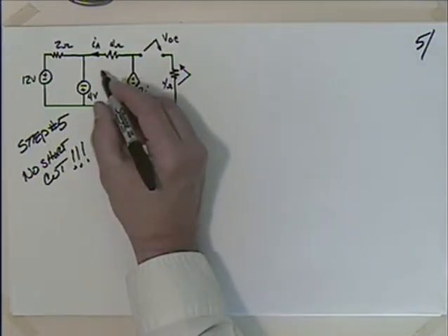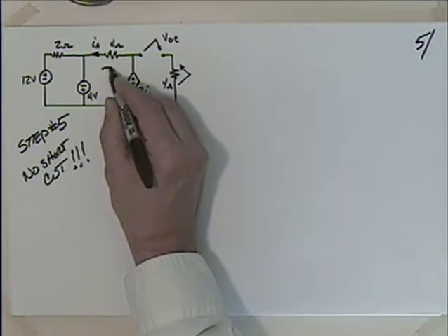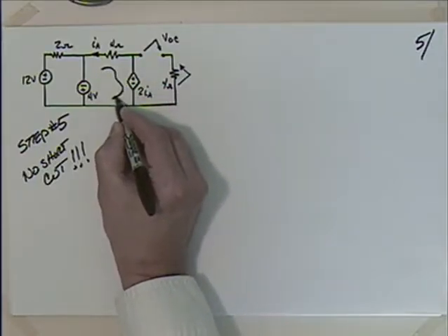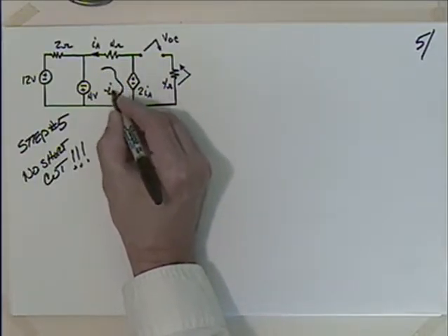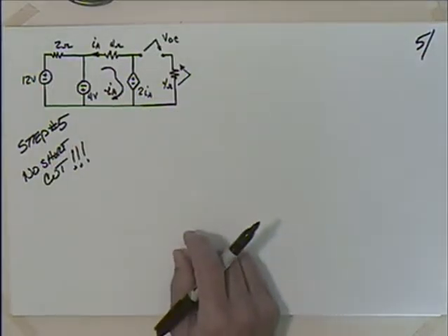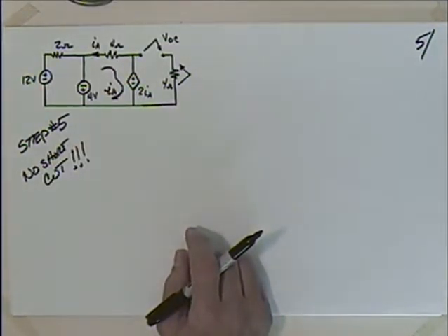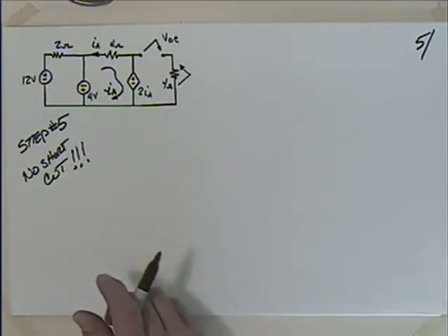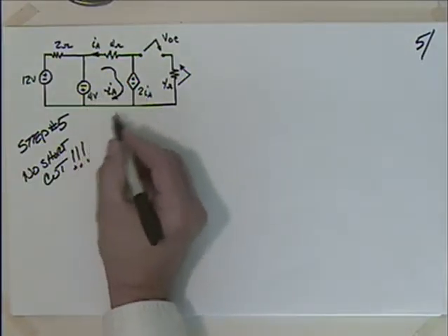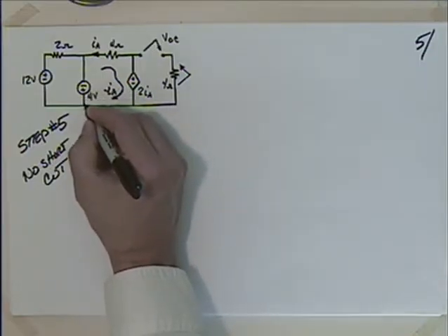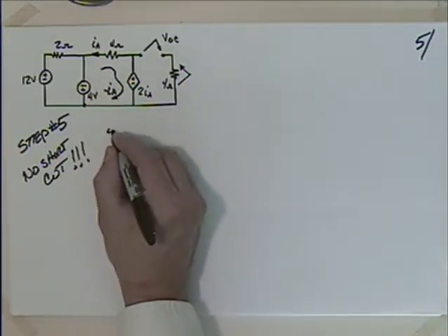I think, again, I'm going to put a current in here. I'm going to say that this current going around here is minus IA. That seemed to work well for us before. So I can work my way through that. Let's see. I'm again going to have starting right there, a drop of 4.